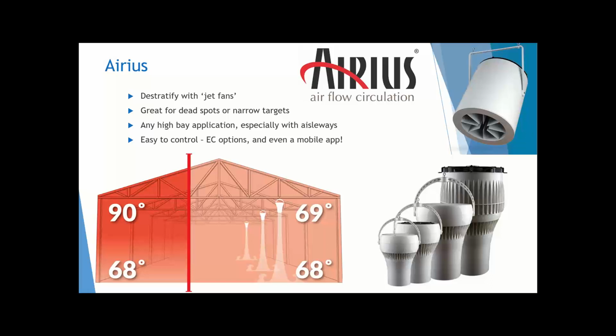They're also really easy to control. There are EC motor options. Also a really good control option is the Smart Triac controller with the AC induction motor instead. There's even a mobile app available where you can control up to 100 fans at a time. So let us know if you're interested in that. We can come up with a layout for you.